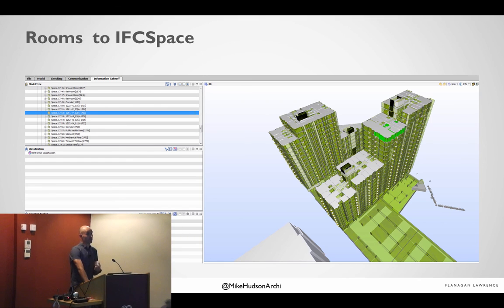The benefit of doing that is when you're starting to export IFC. So I go back to that whole level 2 stuff. They're expecting IFCs from us, where the rooms themselves are entities, and you might be exporting rooms within rooms because you've got an apartment and you've got rooms, and someone's using Solibri to say you've done it all wrong. It allows you to have some kind of upstream thought process in how you're putting data in and out of various vessels in an IFC space.